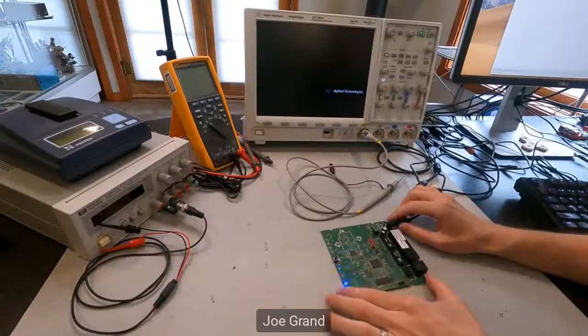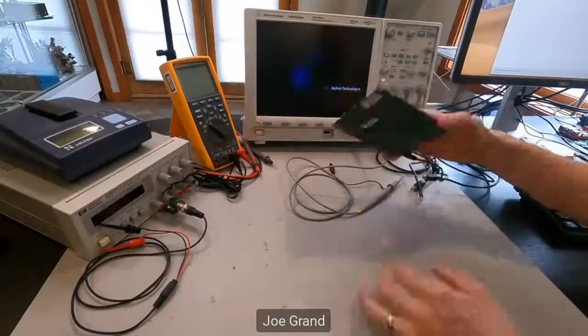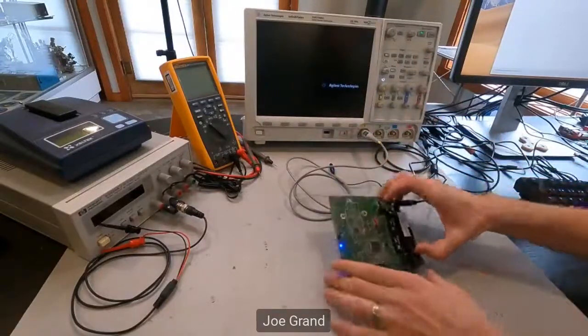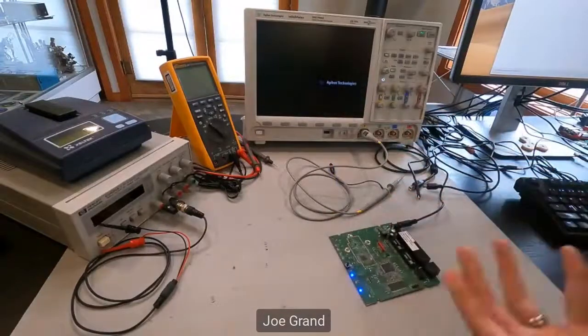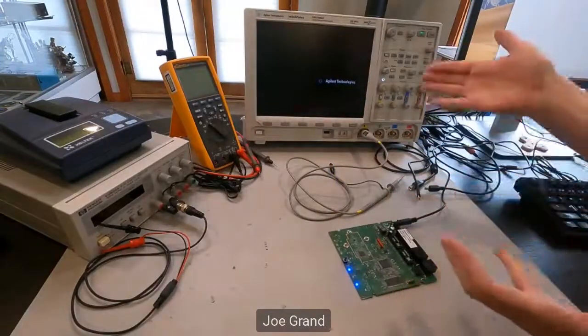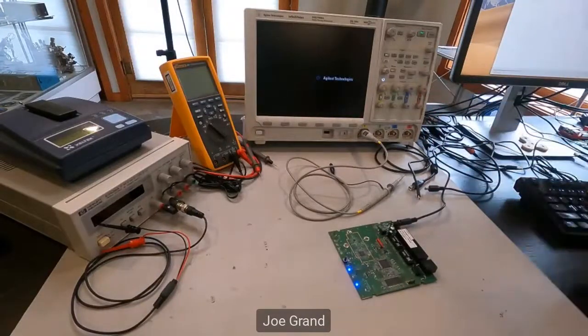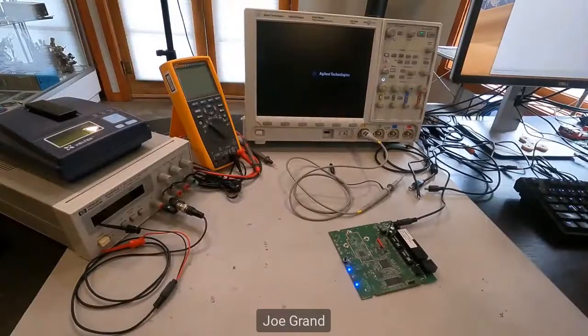Cool. Okay, so what we have here is going to be our little test area, demo area. The first demo I have set up is a Cisco Linksys WRT120N, a little access point, just to show. There are lots of big components on here, so it's easy to poke around. One of the first things I'll do is look at a system and poke around with a tool like an oscilloscope or a logic analyzer to help me understand what activity is happening on a board, what signals are doing things, and what aren't.